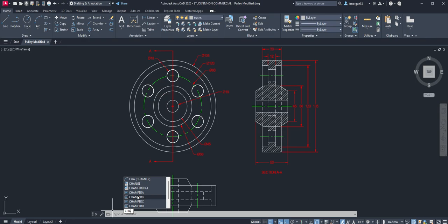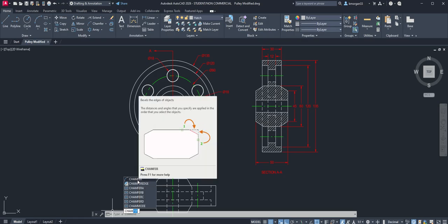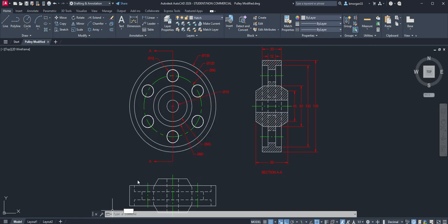CHE, and then of course you can give it an M to get a chamfer. It's actually right here, so you need an M to write it. And of course you can also go copy. It will show up, copy is there. And then of course erase, we did erase. The pencil will show up, and then we break stuff, so that's explode.